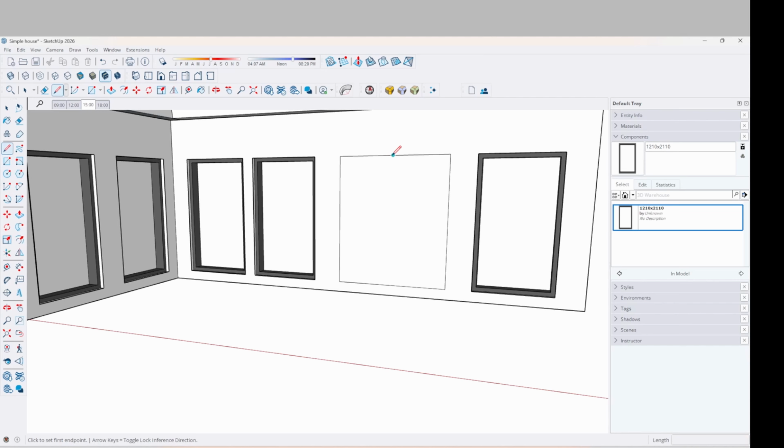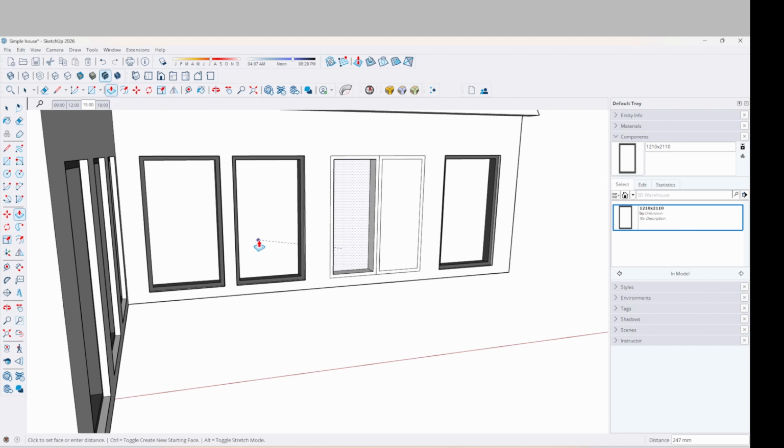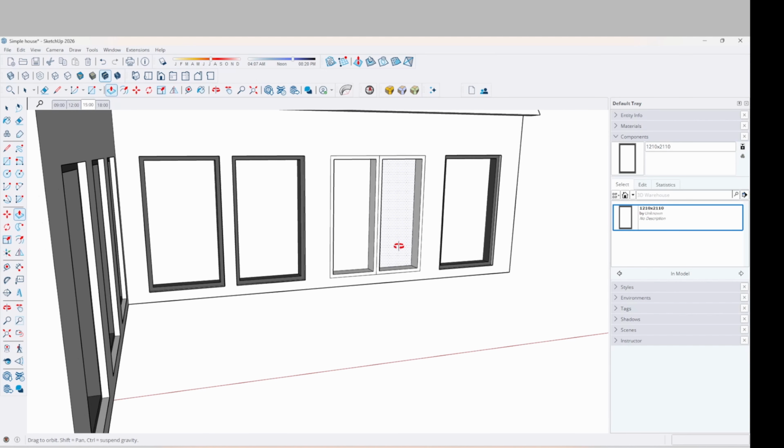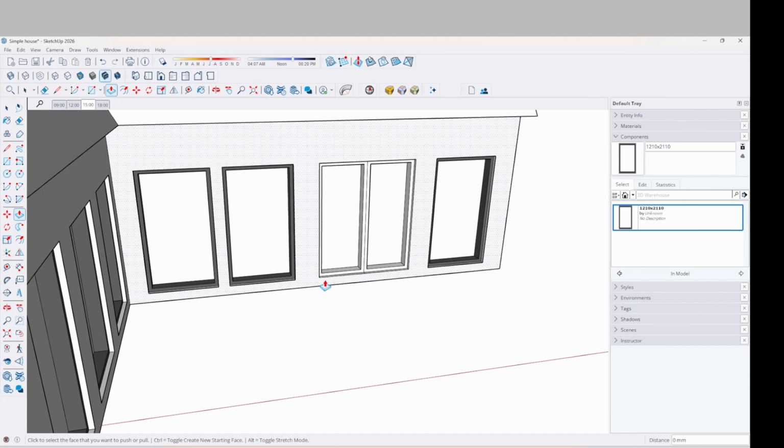And if I'm going to create a double door, maybe I'll put a line down the middle, like this, and then do an offset. Double click so it remembers that it was 60 millimeters like we did on the window frame, and then press the window in. If I don't know exactly the distance, I can hold down shift, wait, like this, and click on the existing face, and then double click on this window, and there you go. Same with the window frame, I can click it and then hold it on the existing window frame and then double click this one to make it the same.